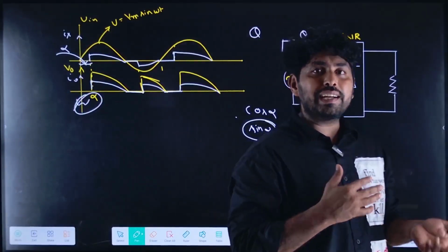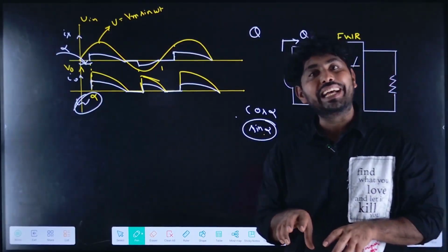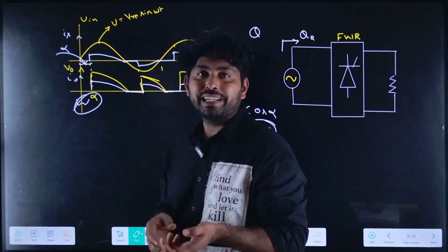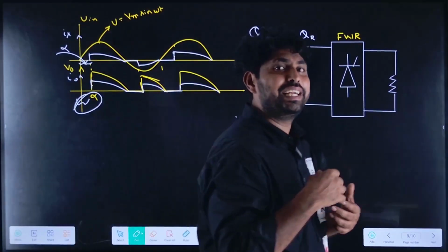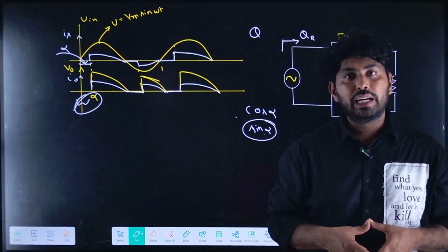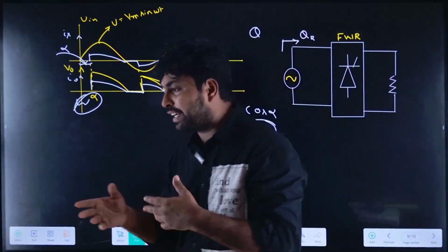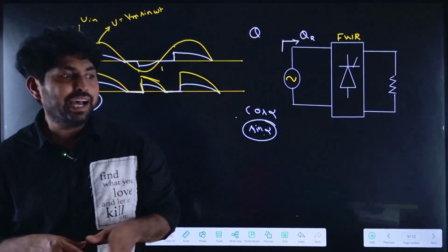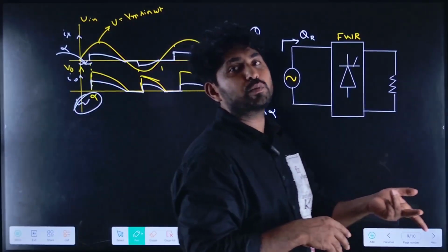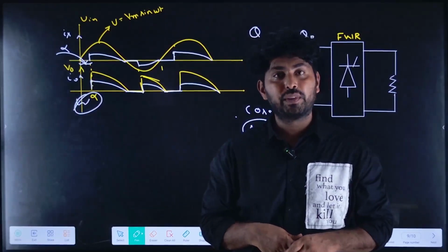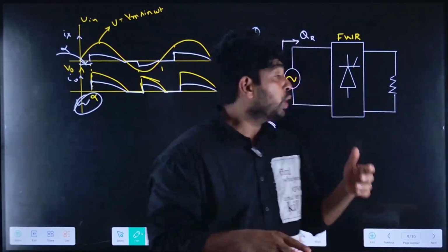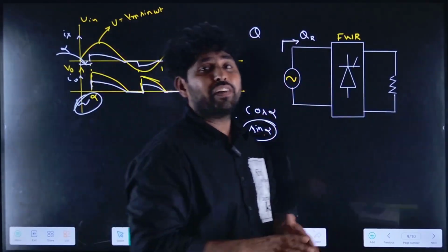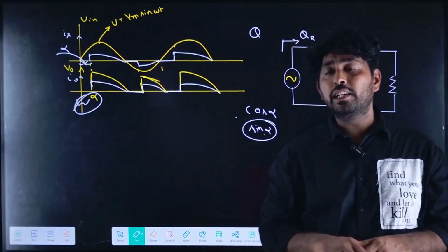In a synchronous generator, based on the excitation, it delivers lagging or leading reactive power. For example, an overexcited, no-load synchronous motor operates as a synchronous condenser. So based on the reactive power requirement, it will be used.